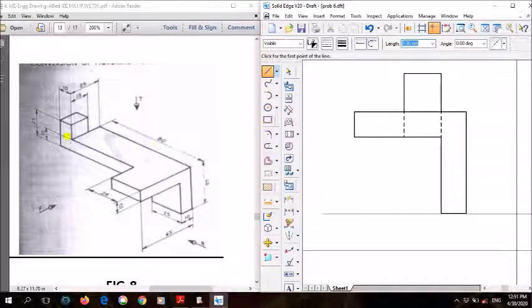Same way again, another surface. So this solid, if you just forget this part, if you just consider only this solid, this solid also has another edge here, right? And on that side there is another edge, so that edge is also not visible. Hence from here you just join a line showing a dotted line. So this is one solid, and this is one solid.